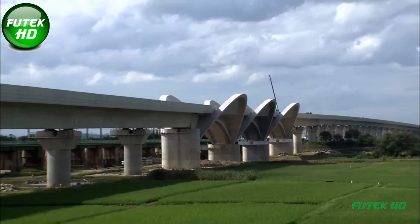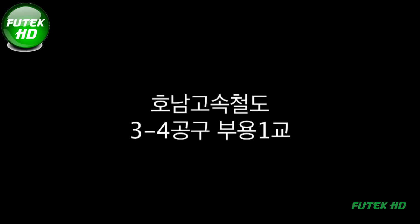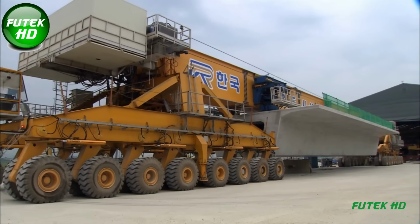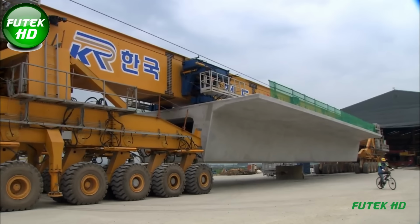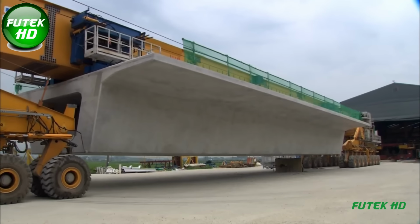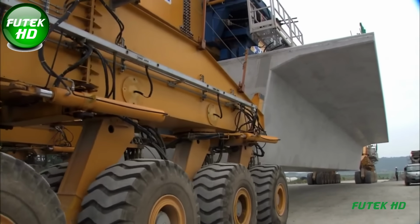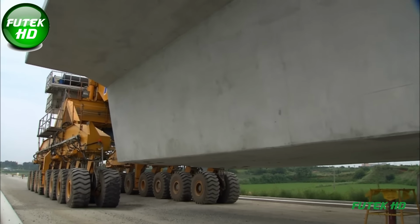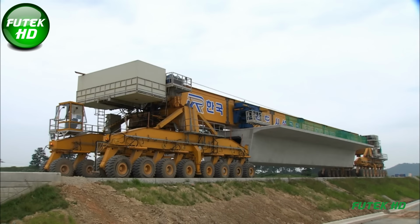The core principle of PSM is to maximize the precision and quality of the bridge components by moving much of the construction process off-site. Factory environments offer ideal conditions for controlling material quality, ensuring precise measurements, and optimizing production processes. This level of control is difficult to achieve in traditional on-site construction, which is subject to weather conditions and other external factors. Once transported, the prefabricated girders are lifted into place using large cranes and other specialized equipment.